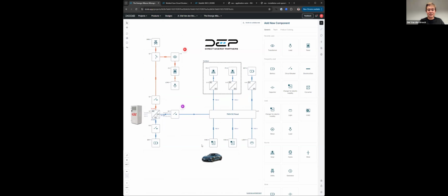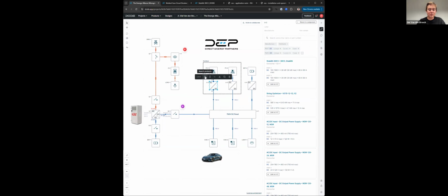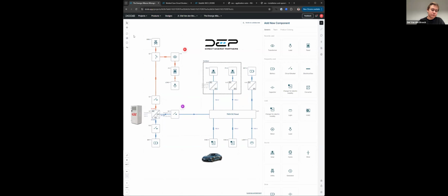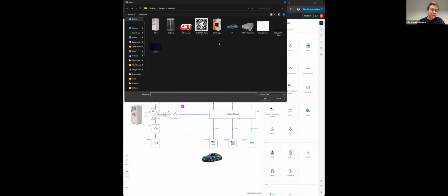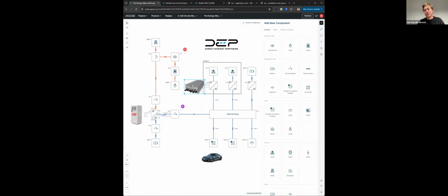But ultimately, it all boils down to the compatibility argument. They are DC sources, DC loads, DC storage, so it makes the most sense to interconnect them at the DC level. And then the second advantage, in my top three of DC system advantages, is that you can transfer more power across the same type of cable infrastructure.